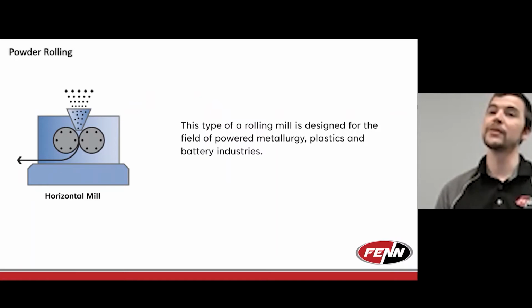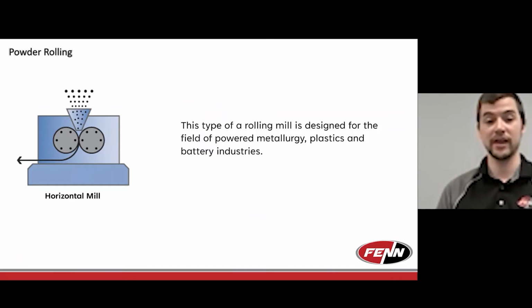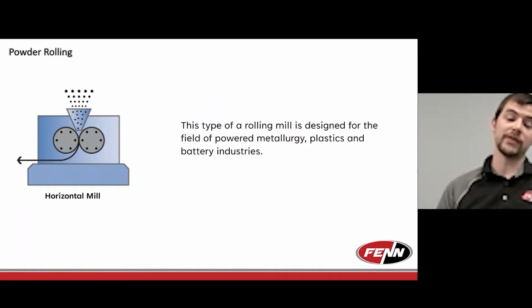And there are other applications where the material starts as a powder, we compress it into a strip, and then it runs continuously in strip form into the next piece of equipment in the line to do further reduction and to add more uniformity to the strip. So powder rolling and strip rolling have some natural ties together. The biggest difference, which you can tell right off the bat even by the reference image here, is that with powder rolling you're using a lot of gravity assist. It's single direction. You can't reverse with powder rolling. So you're running a hopper sifting powder at an appropriate flow rate into rollers, using gravity to assist it in there. And then the rollers provide the necessary compression needed to create it into sheet form.